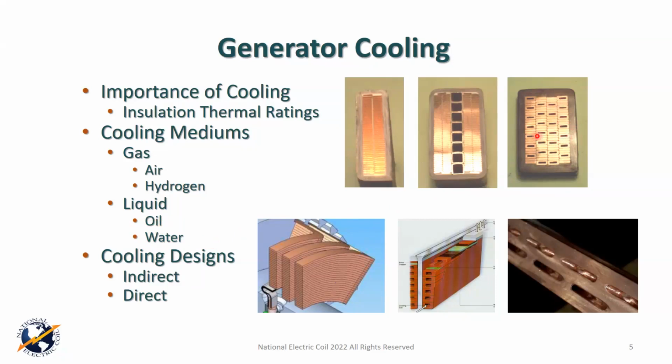It's kind of like what you see over here in the right hand picture. Now, there's some people that ask me, well, I saw a coil cross section and all the segments were hollow. And Howard, some of these are solid in this one. Well, this is a more recent vintage machine from a liquid cooled standpoint. The original machines by pretty much all the OEMs, all of the conductors were hollow. And the reason they did that is they weren't really sure how much cooling they would get from each strand.